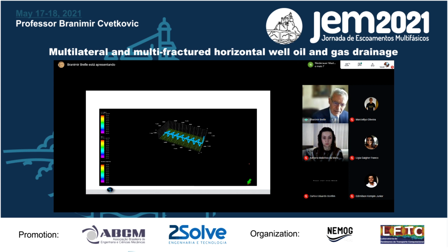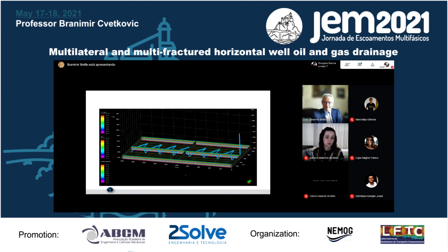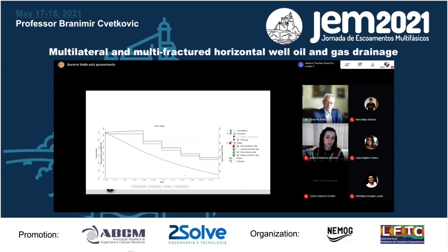the horizontal well with 9 laterals in a very simplified model. That is my study with Eclipse, which I did, I think, last night. So here what I did, I put a horizontal well, I put laterals. This is going to be like we did before, I'm putting 9 laterals along the horizontal well, and then I want to see what my production is. Not per lateral, I'm just interested to see what my production is.